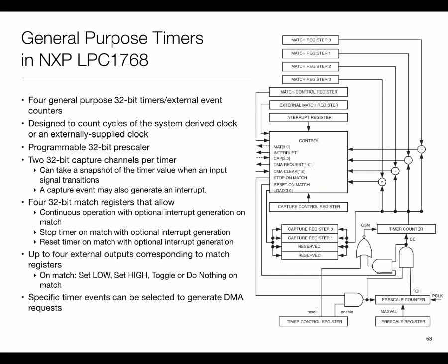I mean, in the sense that for any given frequency, let's say my processor is 100 megahertz. Let me make my life simple. A processor is 1 megahertz. That means a clock cycle is 1 microsecond. Let's say I want to convey values from 1 through 100 at 1 digit resolution, right? So I want to be able to say 1, 2, 3 through 100. So that means my period of my PWM signal must be 100 microseconds, right? So that means I can convey a new value every 100 microseconds only, every 100 clock cycles.